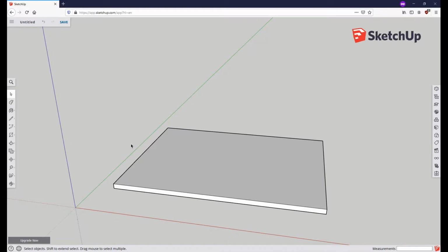The easiest thing to start with are the exterior walls, since this whole thing will be enclosed. So using the line tool here, not the rectangle tool, we're just going to start creating points. And of course, with the measurements, we can simply type 8 feet, not 89, 8 feet. And that creates a nice 8-foot line. I measured my walls in the apartment. They're about 8 feet tall, so we're going to go ahead and go with that. We can always add more on top if we need to.